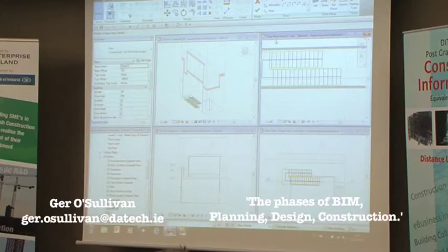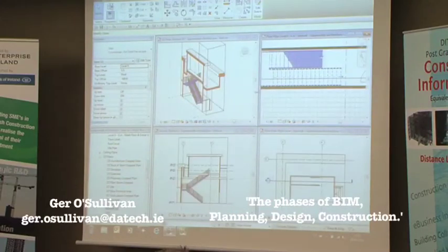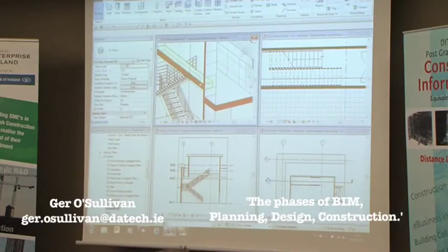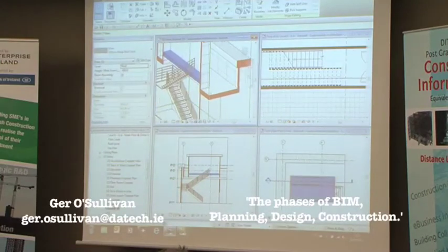So this is my stair done. It looks like it's a 2D sketch, but once we finish the sketch, we should then get to see the finished stairs like that. So again, create it once, do it in one view, and you will get it in all the views you need to see it in. Again, it's got intelligent information associated with it. Unfortunately, it doesn't cut the floor, so it doesn't put the opening in the floor, but we can still do that if we wanted to.